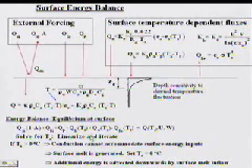There's one key exception: if you get a solution that says the temperature of the surface of the snow is greater than 0 degrees C, that's non-physical, because snow cannot exist at greater than the melting point. What that really means is that more heat is being supplied at the surface than can be carried into the snow by conduction. So if that's the case, the extra energy is going to go into generating meltwater at the snow surface.